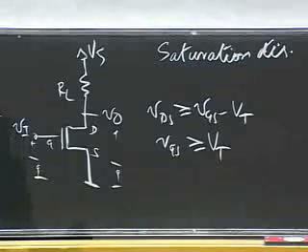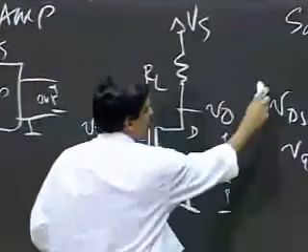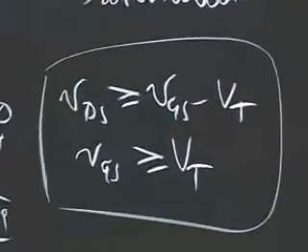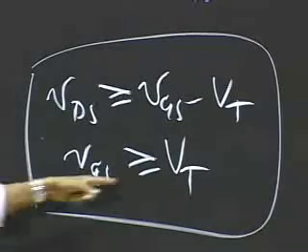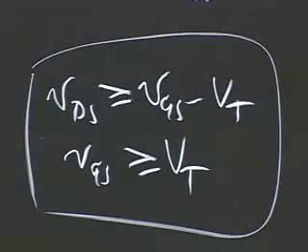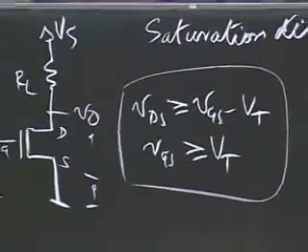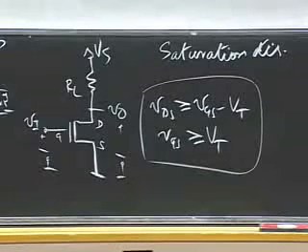Okay? So we've now created a small playground for ourselves where we can build lots of fun little amplifiers and other circuits. And provided our circuits follow the saturation discipline, where for the MOSFET or MOSFETs in the circuit, these expressions are true, then the MOSFETs are going to be in saturation, the current source model applies, and I will indeed be getting saturation.